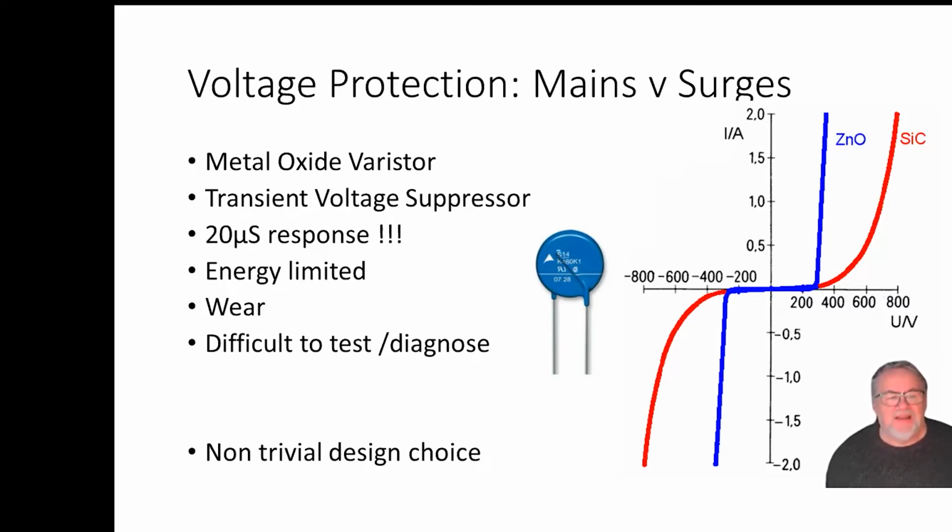The metal oxide varistors are actually an exotic semiconductor. They're designed for voltage suppression, and they're blue. They're always blue. I don't know why they're always blue, but blue is what they always are. And if you look in the back of any power supply, any connection to the mains, you will find these round blue boys, 20 millimeters in diameter, hanging about there. They behave at high voltages. You look at 250, 300 volts before they start to change.